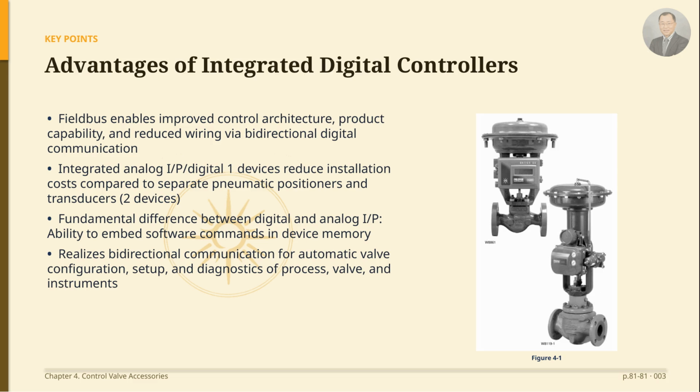Fieldbus technology enables two-way digital communication over the same wiring, which improves control architecture and product capability while reducing wiring. Additionally, using a single, integrated analog I/P positioner or digital controller instead of a combination of a pneumatic positioner and a transducer, two separate instruments, lowers installation costs.